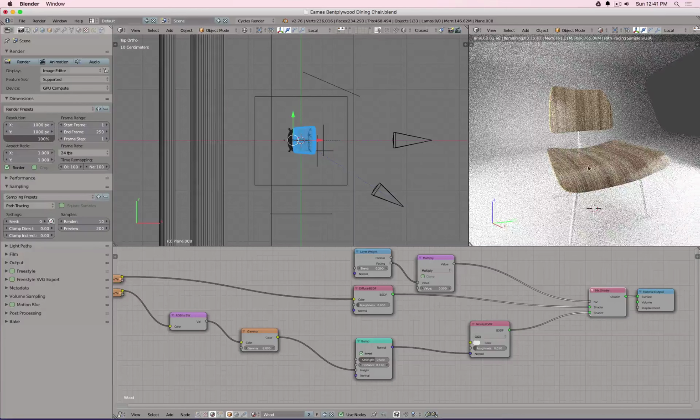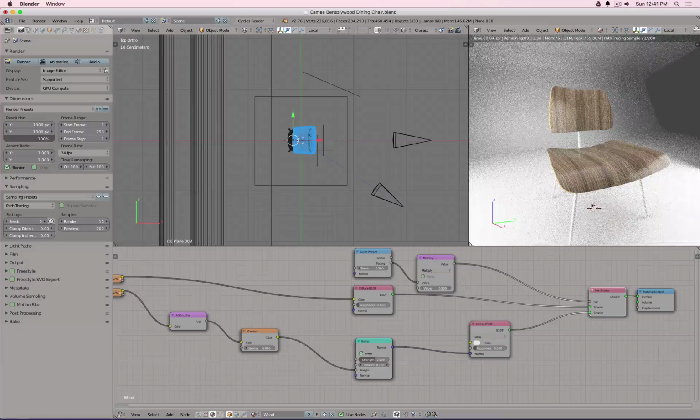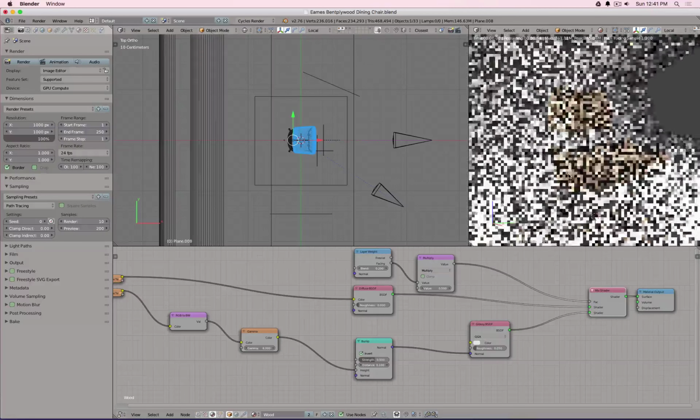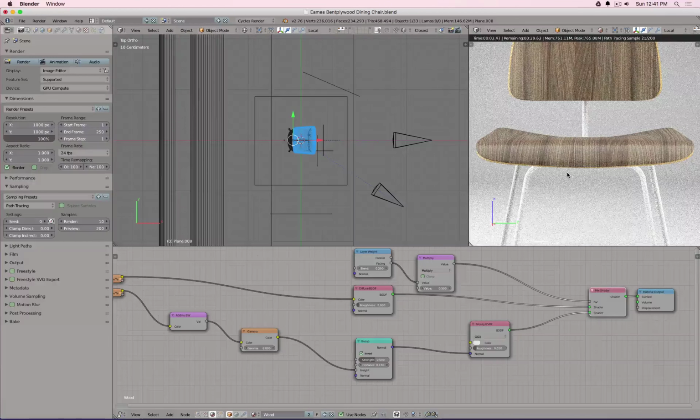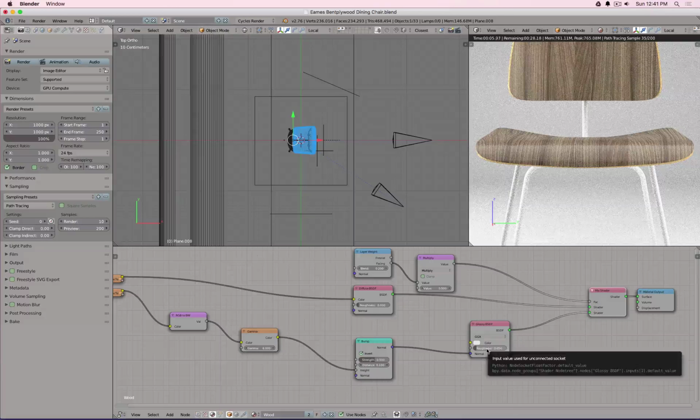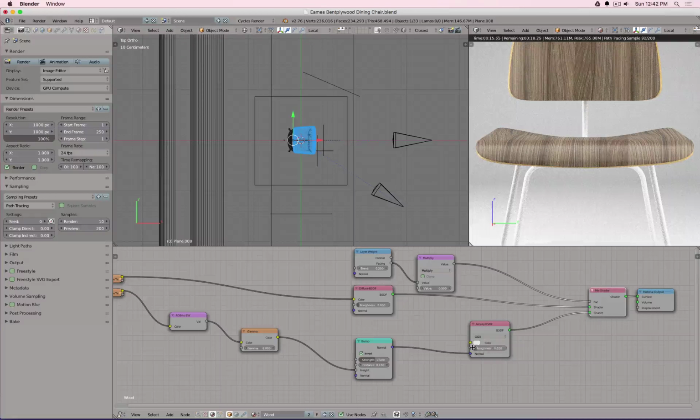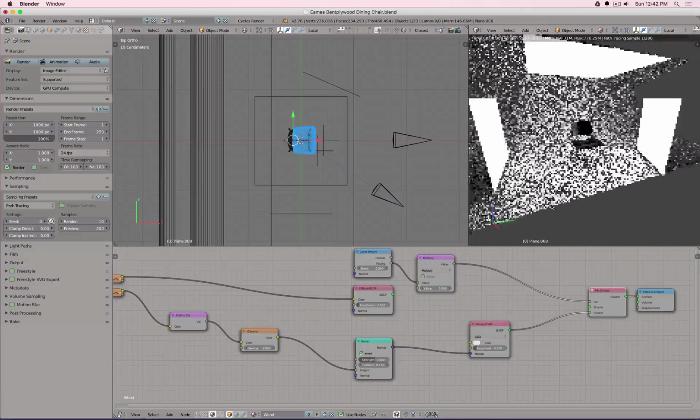Okay, nicely, because we did it for this material, this also applies to that material. So that did it at once. So now the next thing maybe to look at is currently we just have a uniform roughness here. So we could also feed an image into the roughness value so that the reflectivity is also affected. So let's take a look how this might work.